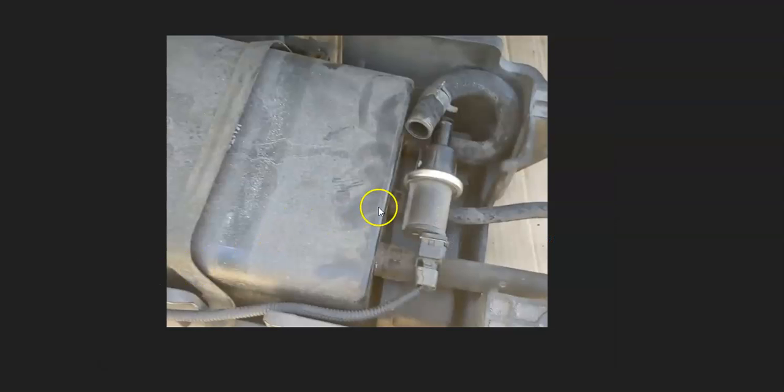But like I said, you can test it if you wanted to. There's different ways you could do that. There's some good YouTube videos on how you go about testing these. But that would be the next thing to do: if you checked all the wiring and all the wiring looks good, there's no opens or shorts or anything like that, there's no blown fuses, then very likely this vent valve has failed. And those would be the most common fixes for a P0446 code.